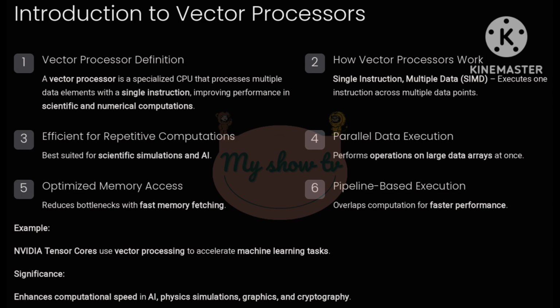How vector processors work. 1. Single instruction, multiple data, SIMD. The same instruction runs on multiple data elements at once, making computation much faster. 2. Efficient for repetitive computations, ideal for operations like matrix multiplication, where the same calculation is repeated across multiple data points. 3. Parallel data execution. Unlike scalar processors, which process data one step at a time, vector processors execute large sets of operations simultaneously.